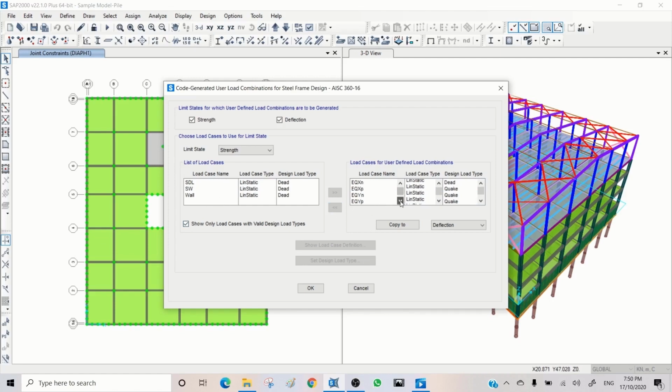So do you need earthquake? Yes, I need earthquake. Live load? Yes, I need. Snow? Yes, I need. So those loads are here. Okay, so for example, you can't see here the displacement loads or thermal loads, and you need to see how you want to add them here.